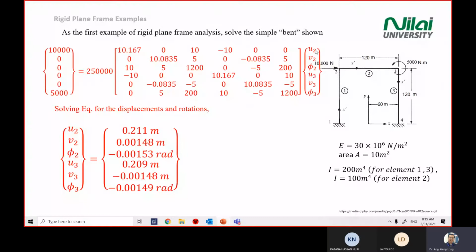Then you need to find the displacement for these 6 values. How do you find the displacement? You need to move this whole matrix to the left, which means you need to do the inverse matrix for this one, and then multiply it with this matrix. Understand? We need to do the inverse matrix. Now we want to input this K matrix into the online portal.